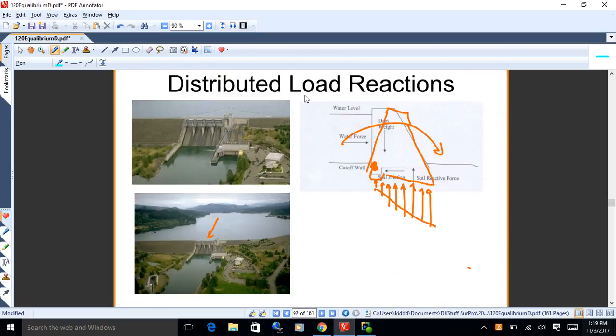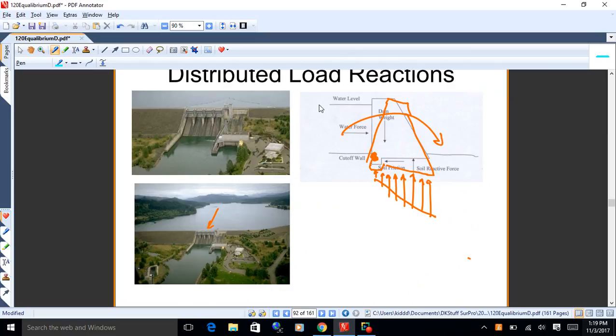Okay. And I did one project, a little bit of a spillway there, and what you do is you figure out the pressure on the soil caused by the dam. The general assumption there is the dam's rotating about its front edge. So you're going to look for the maximum soil pressure that's required to push back. And then hopefully you've got some information on the soils under the dam. And then you relate the strength of the soil under the dam and be sure that it can handle that pressure you're going to put on it when you apply this force here and try and rotate it like so. So what they do, they get out there and they drill holes and pull the soil up and do some testing on it to try and determine its strength,